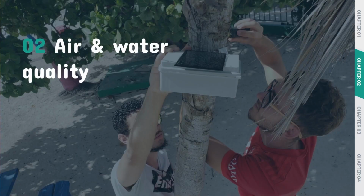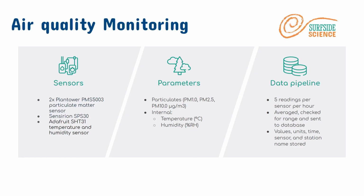Air and water quality. Air quality monitoring. For the sensors, we decided to go with a PMS 5003 particulate matter sensor and with the SPS 30, which is also a particulate matter sensor. And for temperature and humidity, we decided to go with the Adafruit SHT 31 sensor. As you can see, I already mentioned the parameters. The particulates we measure from PM1 to PM2.5 and PM10 in micrograms per cubic meter, and temperature in Celsius,